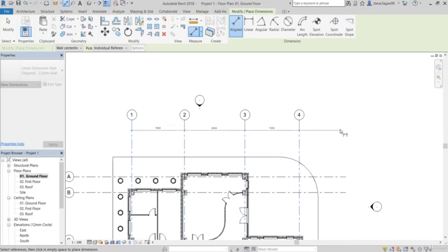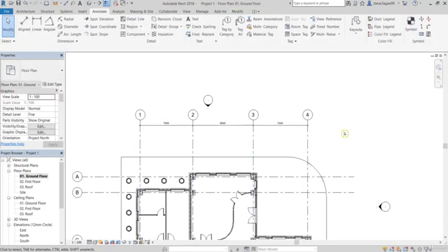The next step is then to position the dimensions where you'd like them to be located. And then finally, to place them, you'll click away from everything on the screen. So if I was to add here, I'd add another dimension, same here. Just move the cursor away from anything else that's not selected and click. If I press enter, escape, or spacebar, it'll just undo everything I've done.